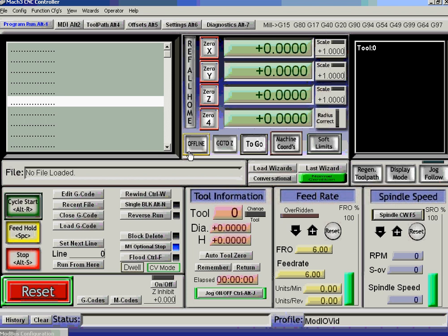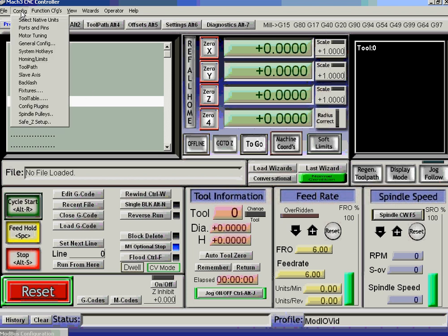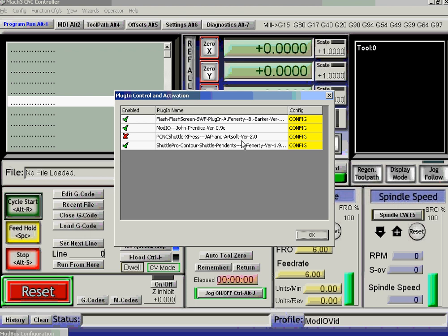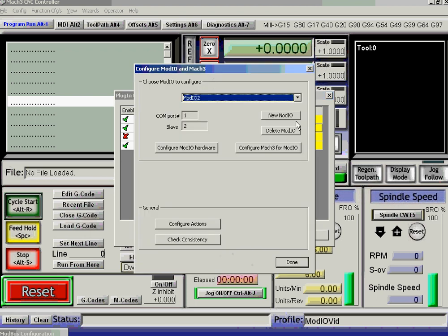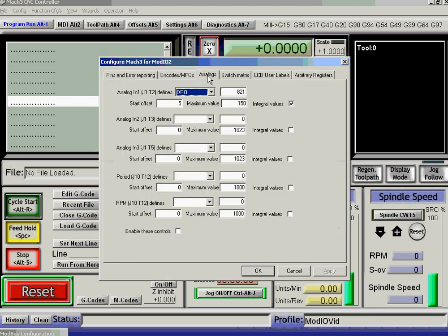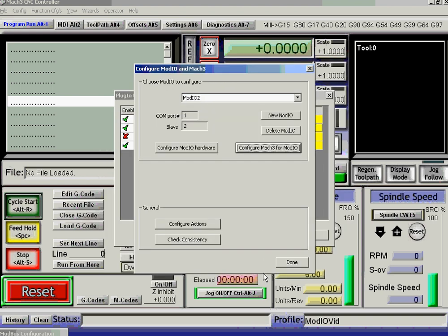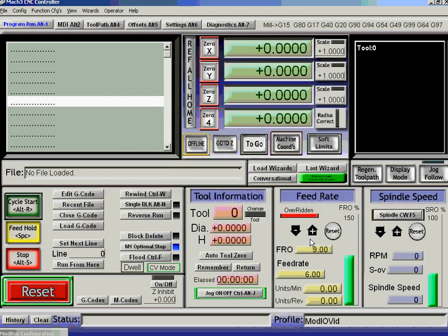I've made the mistake that I make so many times, and you will make. When I was configuring, I've done all that work setting up the analog inputs, but I haven't enabled them. It may be that you want to not use them, whatever the values are here. So if we enable that and OK it and close it down, now as I turn my potentiometer, it's wound